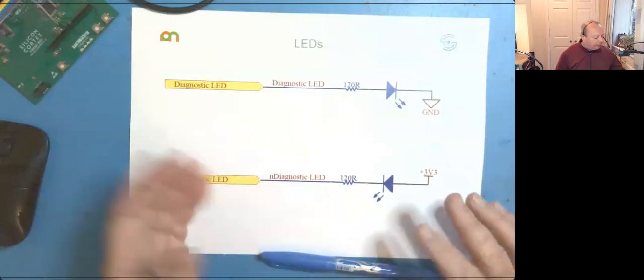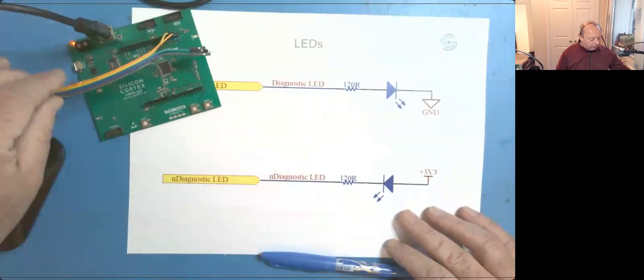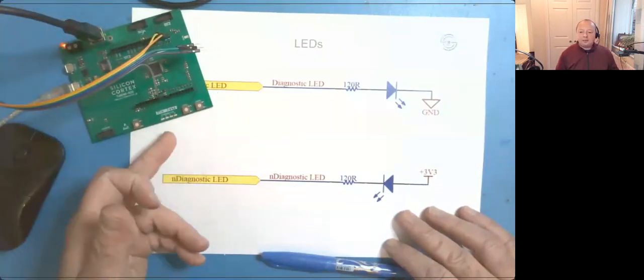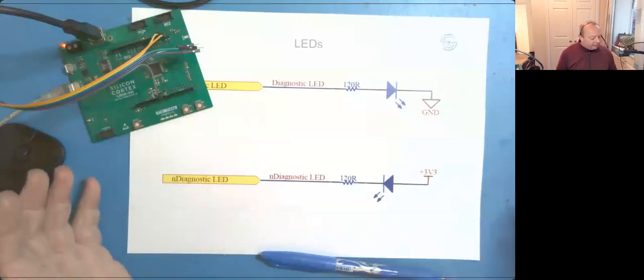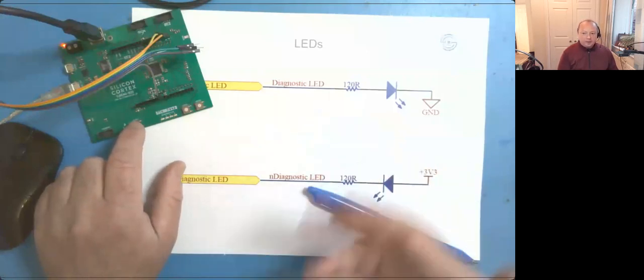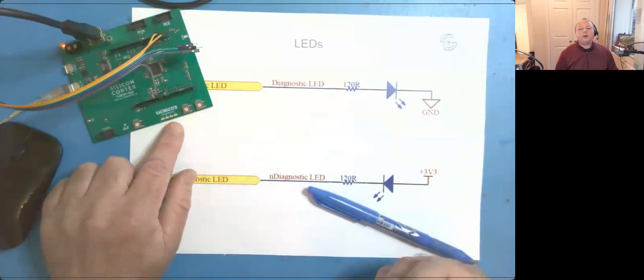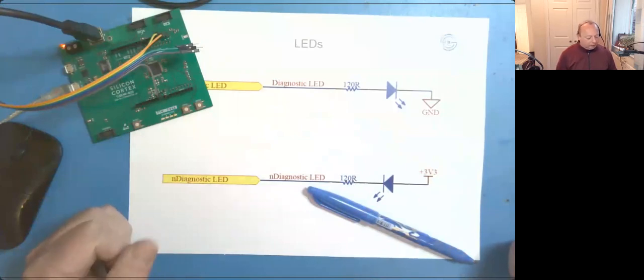Whenever I'm developing electronics, there's a board here. I pulled this one out of the drawer about half an hour ago. I always put LEDs on any microcontroller. It's dead easy to do. With the first bit of code, I always do a simple light sequence, just so I know the LEDs work, just so I know my program is up and running and it hasn't hung.